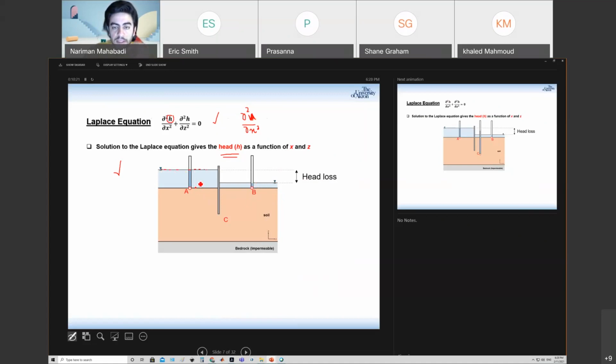And this is saying that I'm going to have a head loss from upstream to downstream, right? The head loss is exactly equal to the subtraction of my total head from A to B. So can you tell me, if I put a piezometer on point C, which is this point, what would be the level of the piezometer? Somewhere between the two. Exactly, somewhere between A and B. Sorry for this piezometer, which is not having the best shape, but we should get somewhere here, right?